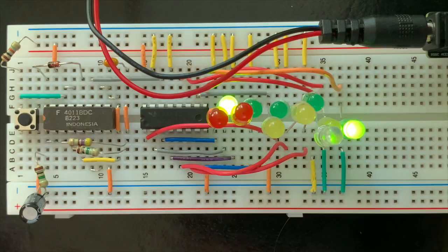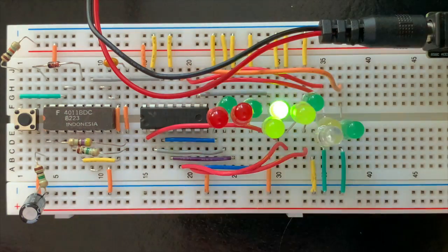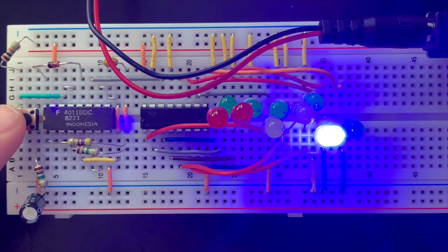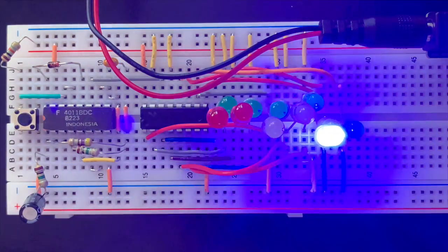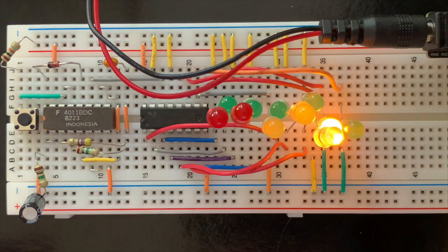As you can see, the LED on the far right is different. It's called the divide by 10 pin and is high for 0 to 4 and low for 5 to 9. Therefore, it provides an output of 1 divided by 10 of the clock frequency.